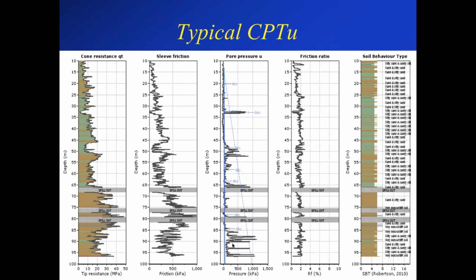Now you're pressing my memory. The next question is, what was the bulk density of the mine waste? That I can't remember, but because it was placed loose, I think we used somewhere between 16 and 19 kilonewtons per cubic meter. The overall interpretation and calculation is not overly sensitive to that number.